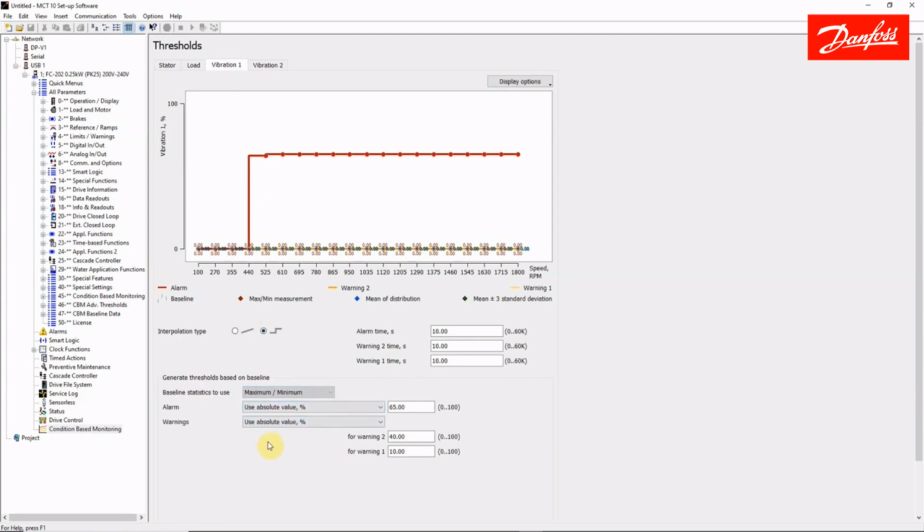As you might expect, we will want to pick up on both extremes of vibration circumstances, whether they have become naturally high, or if the values just become excessive, or if they go to a minimum value. It may well mean also that you've lost a transducer or something to that effect.